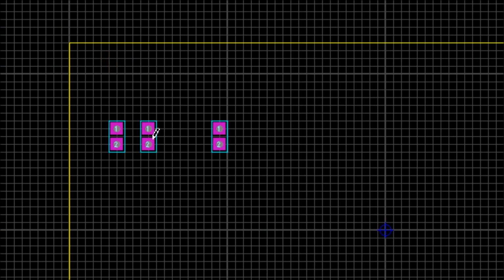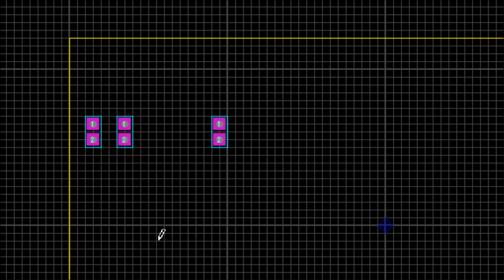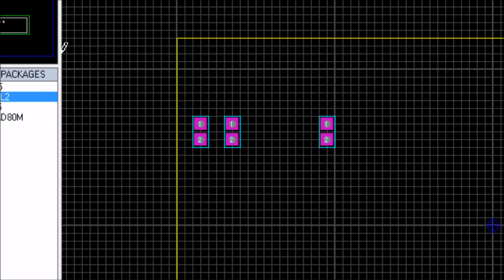So the space here, I have my transformer here, and I have this here. And what are they doing? This is going to be my inputs from 220 or 210 volts, for guys in some countries using 210. Remember, I told you in my country I'm using 220. And this space here is where my transformer will be, because I don't have the transformer on the PCB. And this is going to be the output of the transformer entering here. And remember, guys, you should be creative. So don't ever get confused.